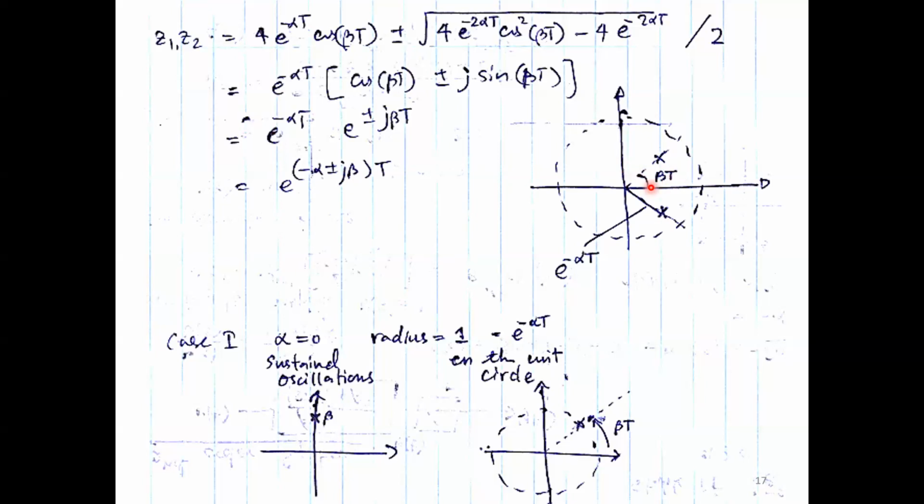So when you have a long time between samples, by the time you take the next sample, the signal has undergone a fairly big angle. That's why you need to make sure your t is not that long, so that you're not missing any useful information of the signal. Eventually, your discrete version of the signal must represent closely the continuous time signal, which is the original signal.